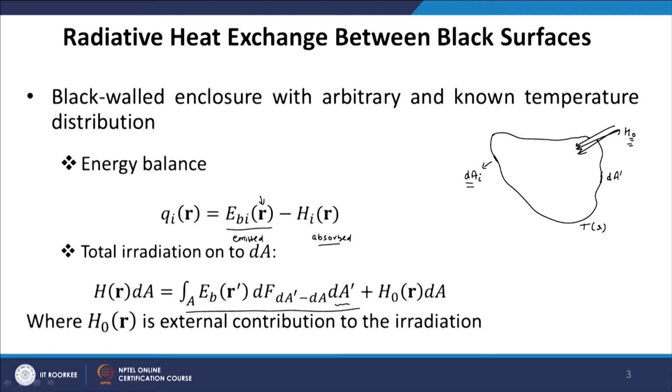So, we have to look at the view factor between these two areas. Energy emitted by this surface times the view factor times the emission power integrated over the entire area of the enclosure, plus outside radiation H naught falling on this area dAi. So, that is the total amount of energy received at surface dA.